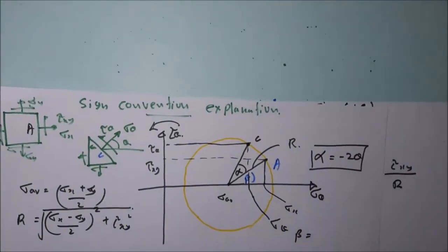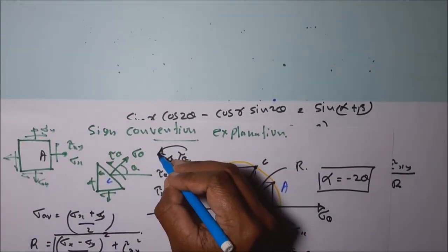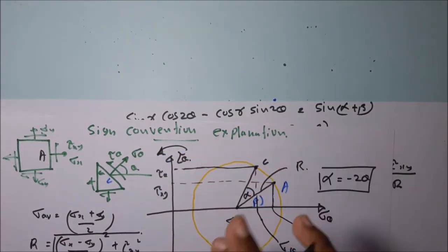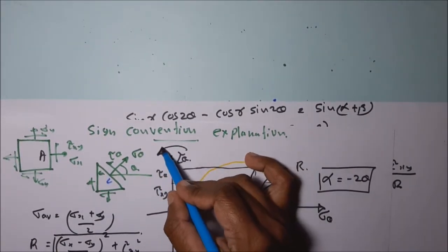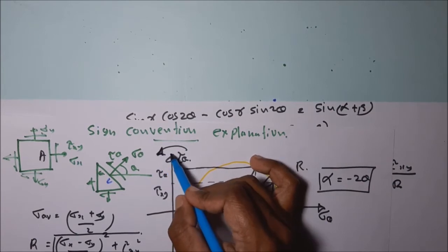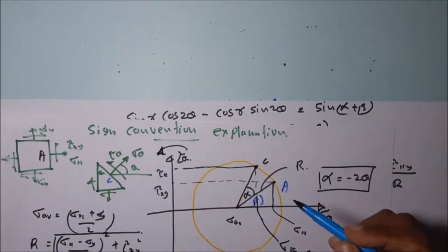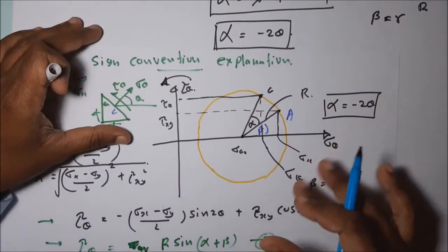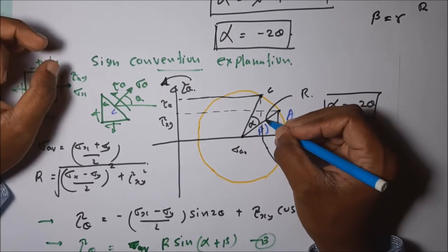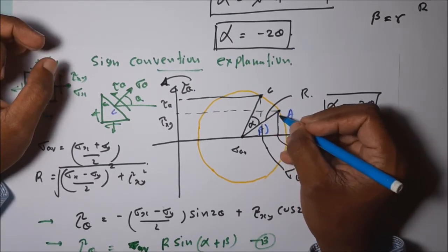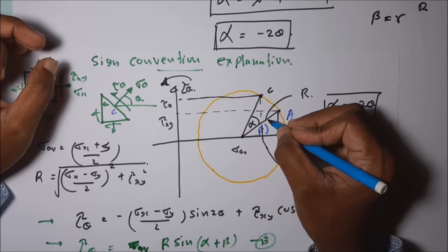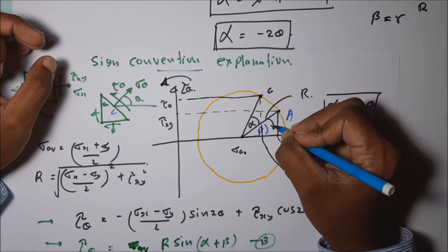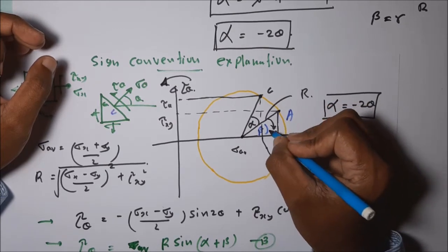What it means is, when drawing the Mohr circle diagram, if we take the shearing stress measurement in the anti-clockwise direction as positive, we have to measure the angle clockwise, and the angle is also doubled.